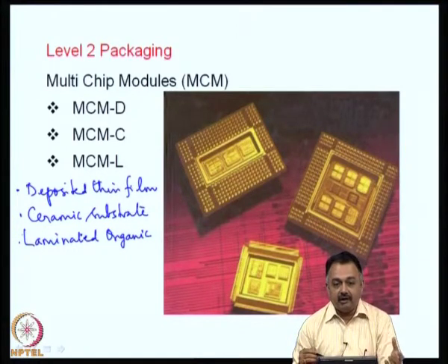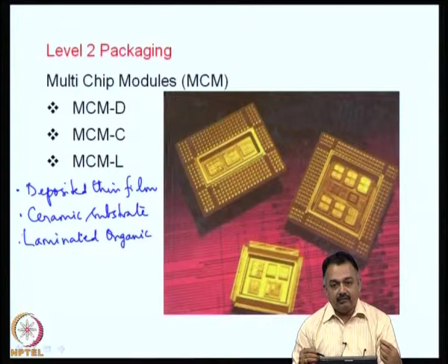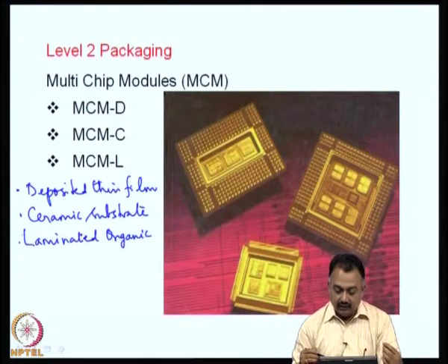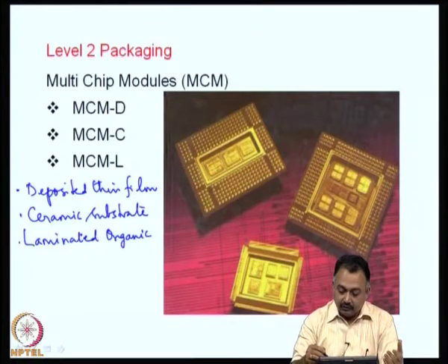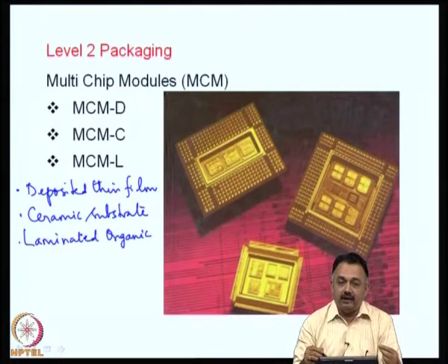It can be from different manufacturers. Okay. Then you mount them on a same substrate, interconnect them, package them, and then specify to the manufacturers of the multi-chip modules, the foundry, and then tell them what kind of interconnection format you require, whether it should be a pin, whether it should be a lead, or whether it should be solder ball. So, that is how the process goes.